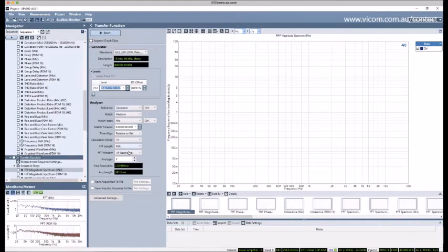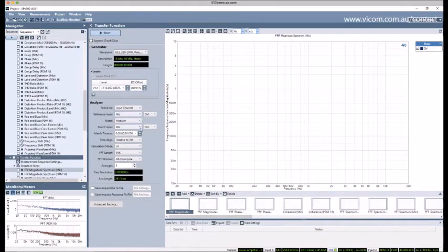The next things, there are a little bit more settings here than in a typical measurement in APX. The reference is the signal that's going to be compared against. In this case, I'm going to set the reference to be one of my input channels, and I'll start with the reference being our analog reference microphone.